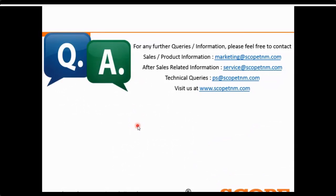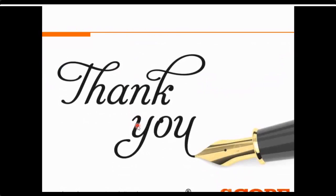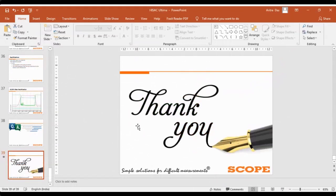Now, concluding here, I would like to add some more things, particularly some of the questions we have received. People are asking about the PIR. PIR is pre-insertion resistance, particularly in 400 kV or 765 kV circuit breakers. In our equipment, we have given the facility to measure the contact timings of the pre-insertion resistance also.